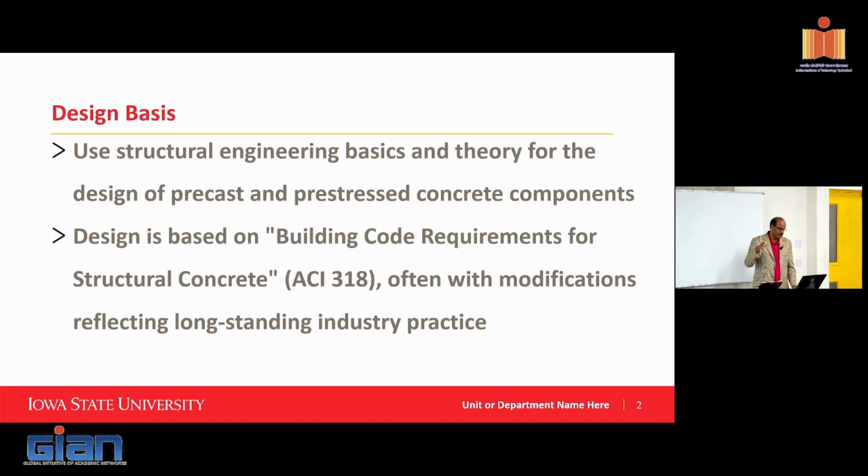Because it's concrete, the design is based on building code requirements for structural concrete. So yesterday I mentioned that the handbook is basically an overarching thing, but you still have to follow the International Building Code if you're doing the building design, and then ASCE 7 for the loads, and then concrete design will be according to ACI 318. But starting from 2025, that requirement will be, instead of 318, it will be 319, which is dedicated for precast.